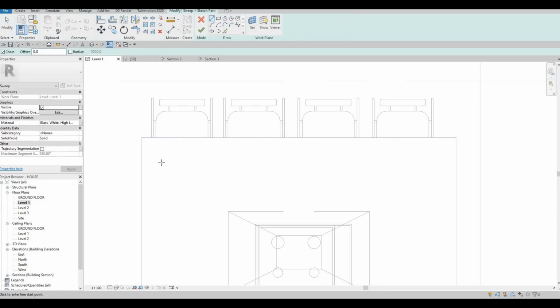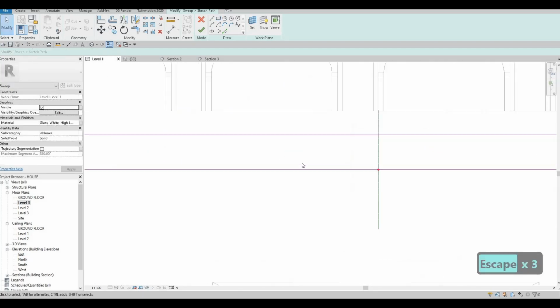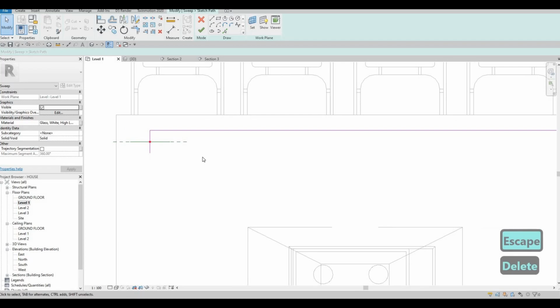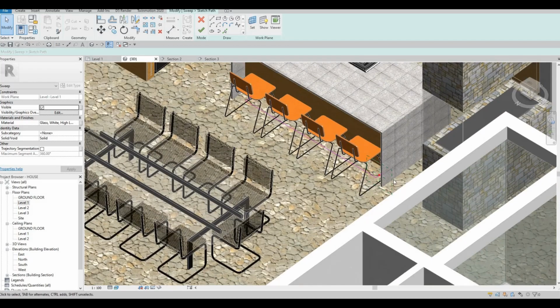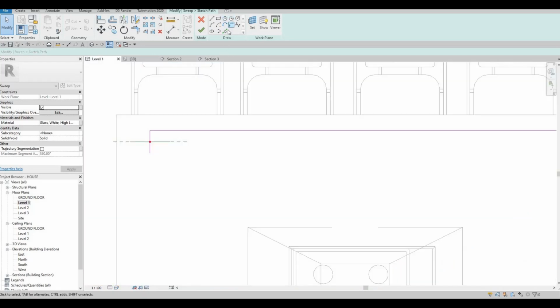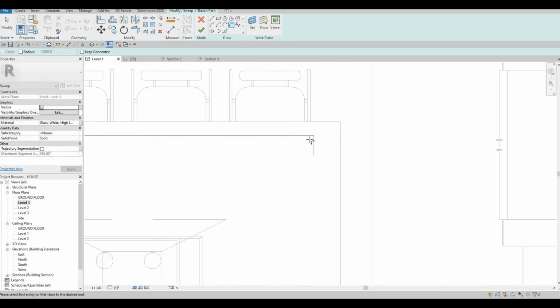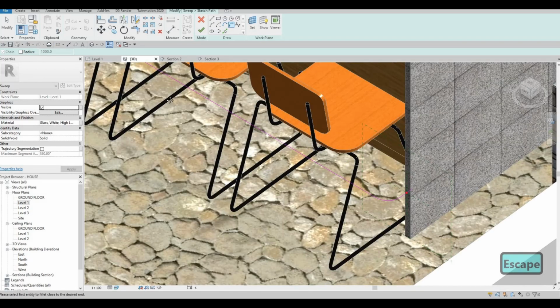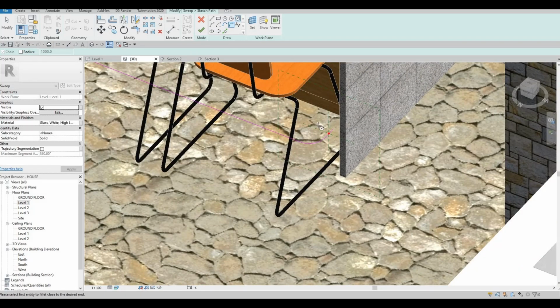Sketch a path. I'm gonna sketch this one right here. Make it a rectangle first. Somewhere right here is the location. I'm gonna delete this one, and let's go onto this part right here. I'm gonna curve it. So to curve it, I'm going to use fillet arc, and then maybe 60, and then 60 here as well. So now that it's curved, we could go to 3D and then create our circle right here.